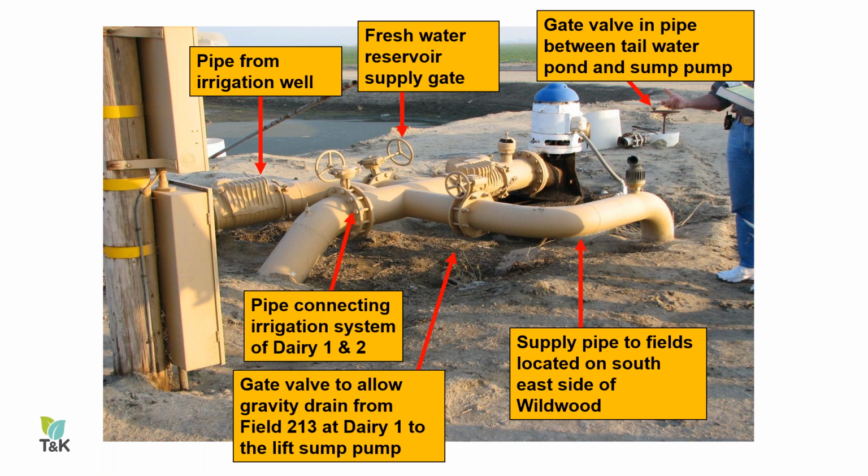But the real root cause seemed to be this gate valve was inappropriate for excluding and dealing with the solids that might be in the wastewater lagoon water that's being transferred around to different fields in proximity to the production field, and was fine when it was first put in, but it was the wrong type of gate valve, and then wear over time allowed it to stay perhaps open, and when water was being sent to the field, actually drew in water from the dairy side.